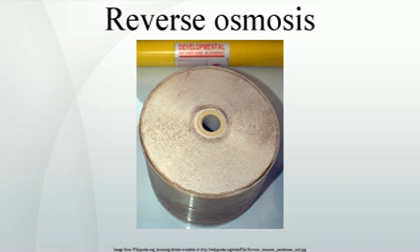As such, the spiral wound design does not allow for backpulsing with water or air agitation to scour its surface and remove solids. Since accumulated material cannot be removed from the membrane surface, systems are highly susceptible to fouling and loss of production capacity. Therefore, pretreatment is a necessity for any reverse osmosis or nanofiltration system.